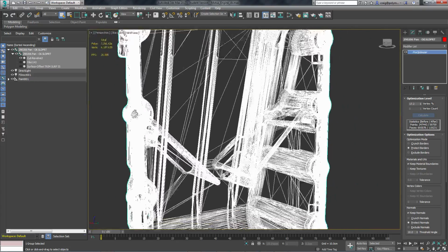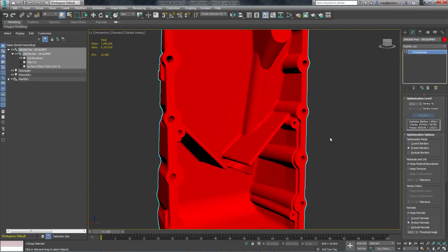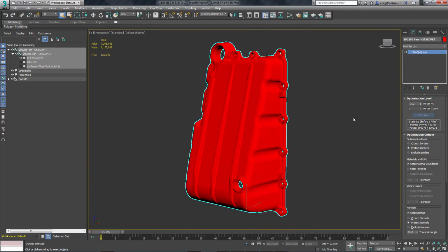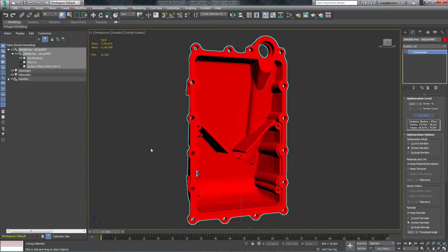But this really would be a job for spending the time to make sure that the part still has its accuracy represented. And as you can see here, we're looking quite decent in here, but we'd really want to have other pieces to make sure that they line up and they fit in these holes here, for example. So we've just broken this down here by about almost 90% rather quickly on the vertex count on here as well as the faces.